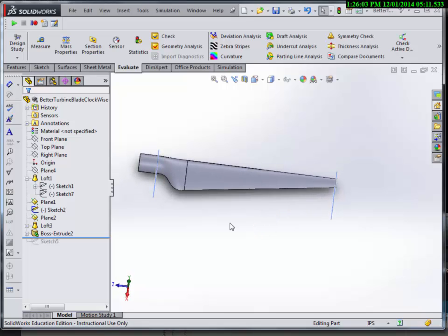Because my printer won't go up above 9 inches, I would then put a plane in the middle and then add what's called a split relationship and to split it in two. That's enough for this one.